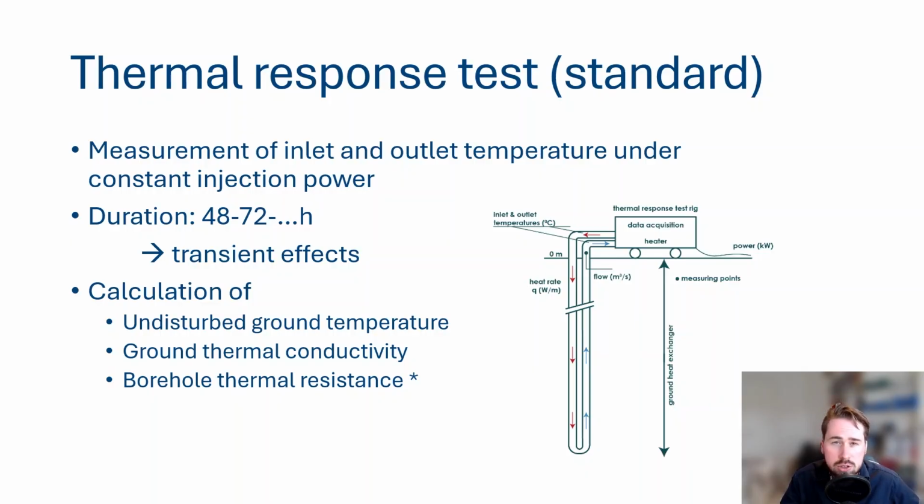Then you let this rest for a couple of days so that your borehole comes again in thermal equilibrium with the environment. So after a week, for example, you come back with your thermal response rig, which you connect to the borehole, and you let the fluid circulate. And you measure the temperature. And once you've done that, you start the electric heater and inject a constant power in the ground. And you keep measuring this in and outlet temperature for 48 to 72 hours.